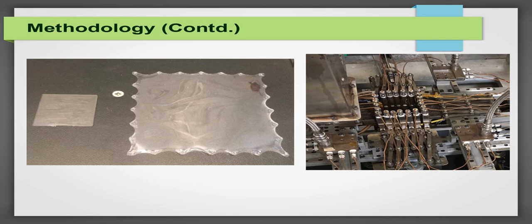Okay, this slide further illustrates the biaxial stretching of the sample. The first picture shows an unprocessed sample side by side with a processed sample. The second picture shows the clamps of the biaxial stretching machine. To process the sample, you clamp the sample in the clamps of the machine and set the machine to heat it to a temperature higher than the glass transition temperature. Then the machine will stretch it to a preset stretch ratio. Because of the heating, the clamps are able to dig into the sample so that during the stretching, it doesn't lose the grip.